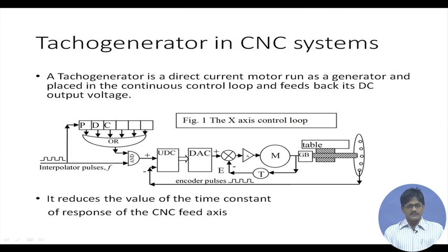So, a definite number of pulses are going to be passed through, and it is then going into the control loop for continuous control. Now, continuous control first of all is taking care of the fact that the particular velocity to be attained is achieved and maintained, say in case of linear interpolation, and also this control loop ensures that the steady state velocity is attained within a very short time.